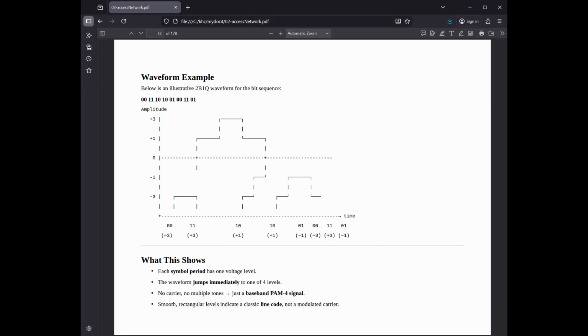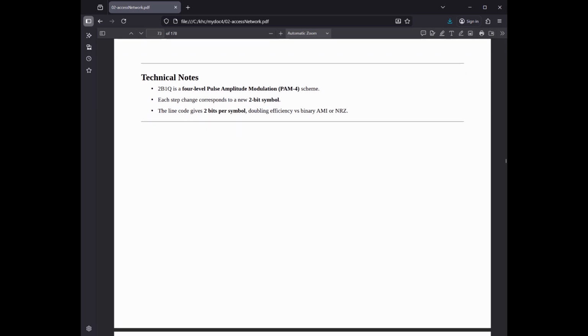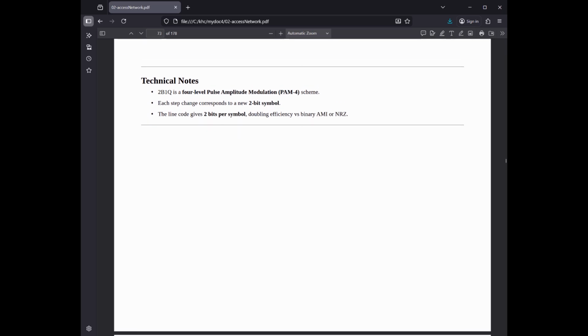3. Wide, fixed-shaped spectrum. Modern modulation schemes like DMT, used in ADSL/VDSL, are considered very spectrum-friendly because they are surgical. DMT can turn off specific frequencies that are known to interfere with amateur radio or other DSL lines. 2B1Q is a blunt instrument. Its power is spread across its entire operating range, up to 80 kHz or 240 kHz, in a fixed way. You cannot notch out a specific frequency with 2B1Q to protect a neighbor's service.